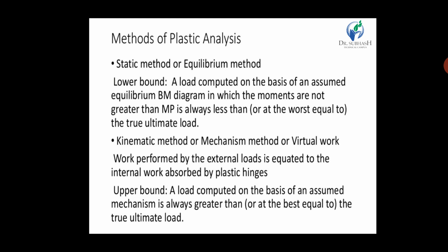Now the second is the kinematic method, or mechanism method, or you can say virtual work. The work performed by the external loads is equal to the internal work absorbed by the plastic hinges. The upper bound: a load computed on the basis of an assumed mechanism is always greater than or at least equal to the true ultimate load.